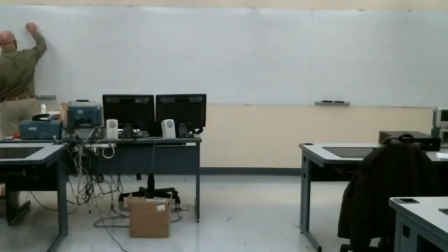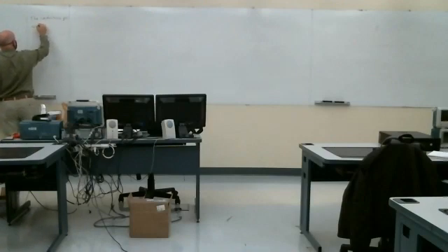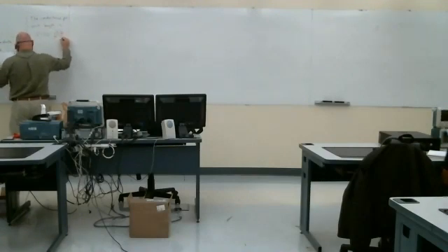And squeeze this in here. The conductance per unit length, G prime, is equal to G over L. It's 2 pi sigma S over the natural log of B over A.